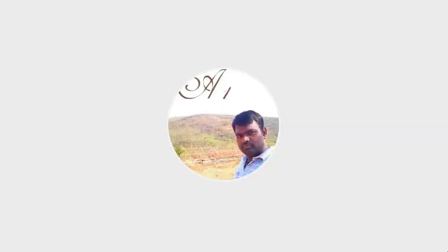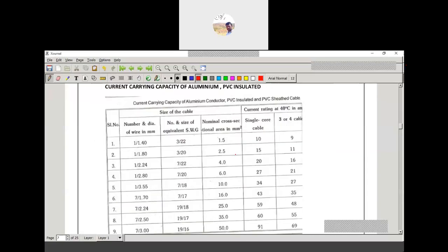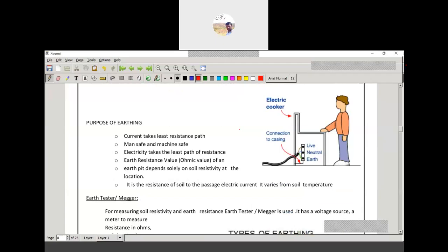So we can see here the HT type. Here conductors are there, a group of conductors, and each conductor has insulation. Around that we have separate insulation. Here is the filler material, insulation for each core, and belt insulation around the three conductors, and the lead sheath around that. Here we can see bedding, which is around the lead sheath, and then steel wire armoring. This armoring is used for mechanical protection. Whenever any external force is applied mechanically, we have to protect the conductor with the steel tape. And at the last there will be a rubber sheath serving material for external protection.